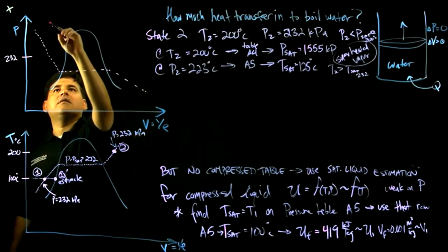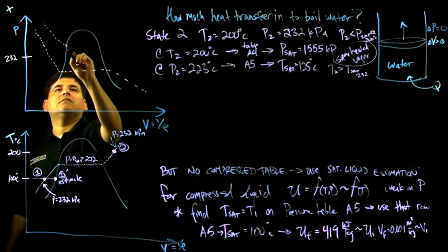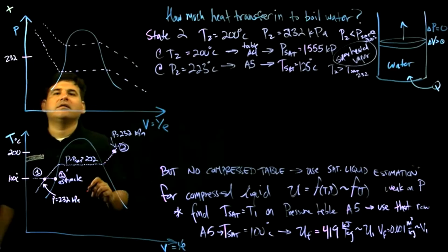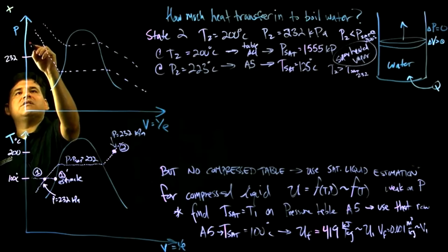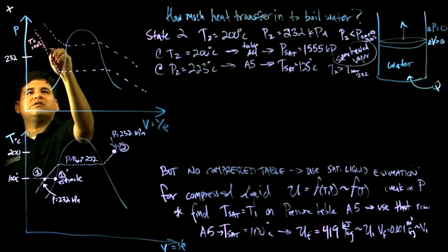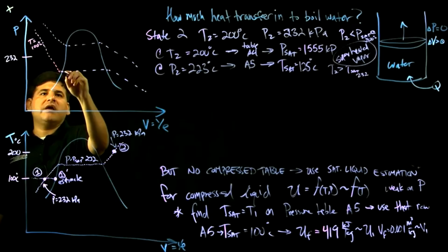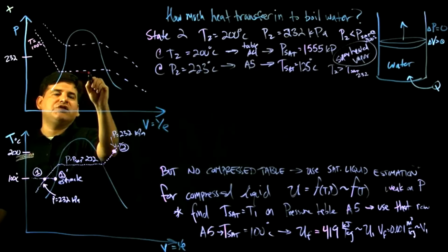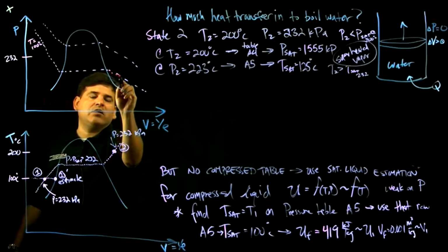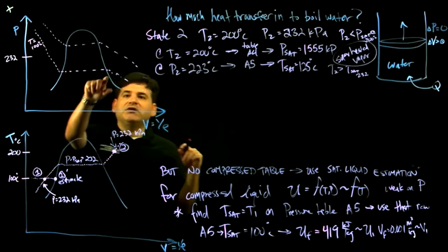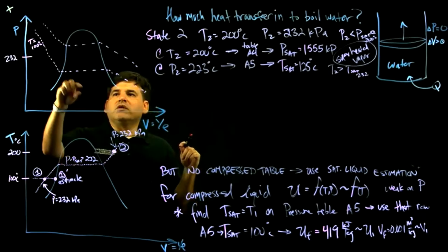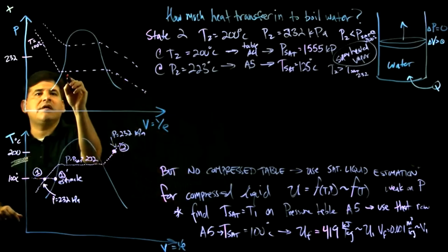Something like that. So, as a matter of fact, this is 100 Celsius. T equals 100 Celsius. So it's 100 Celsius here. The pressure goes down to keep the temperature constant, and then during phase change, the temperature and pressure both stay constant. And then when you're in the gas phase, the pressure decreases for the same temperature as you go this way. So these are lines of constant temperature.